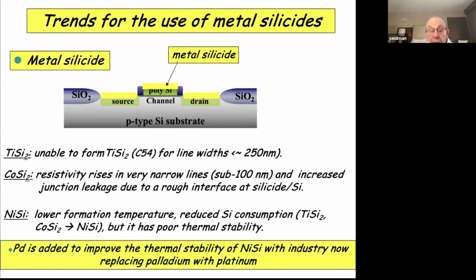So what's done is to add some palladium to improve the thermal stability of the nickel silicide, with the industry now replacing palladium with platinum, which is expensive, but the customer pays for that.